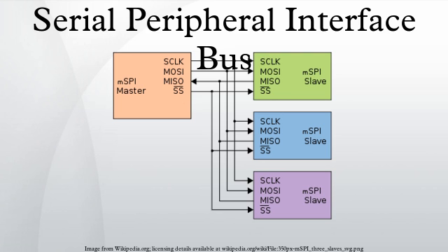Applications: the board real estate savings compared to a parallel I/O bus are significant, and have earned SPI a solid role in embedded systems. That is true for most system-on-a-chip processors, both with higher-end 32-bit processors such as those using ARM, MIPS, or PowerPC, and with other microcontrollers such as the AVR, PIC, and MSP430. These chips usually include SPI controllers capable of running in either master or slave mode. In-system programmable AVR controllers can be programmed using an SPI interface.